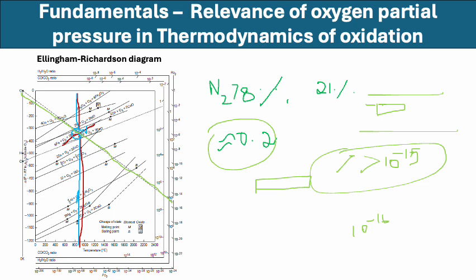But this is very important, and the reason the parabolic growth kinetics is experimentally relevant is because we can predict how much oxidation will take place over time, and that is important for industries to predict the service life of the component. I can do experiments for 1000 hours, but industrial service times are much greater than 1000 hours. So I cannot keep doing experiments to 100,000 hours. So that is not possible.